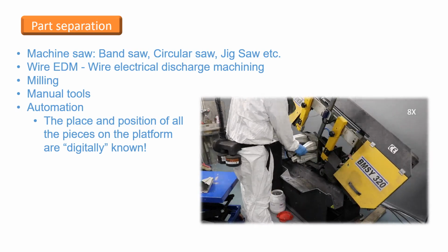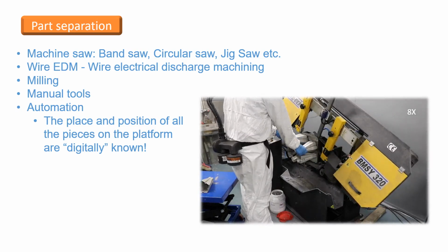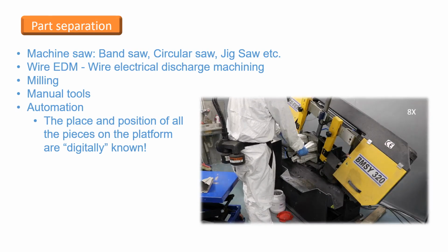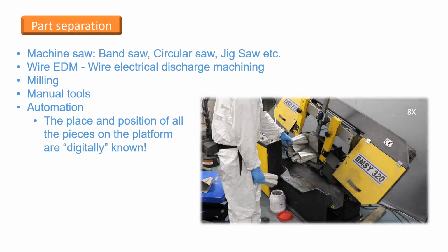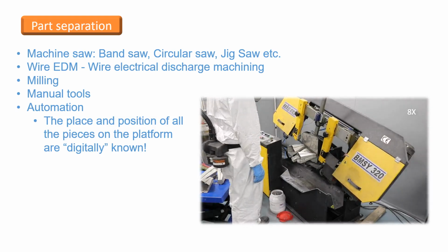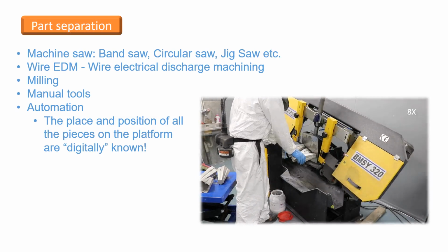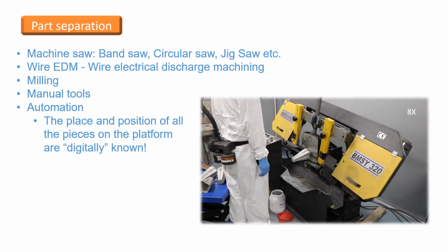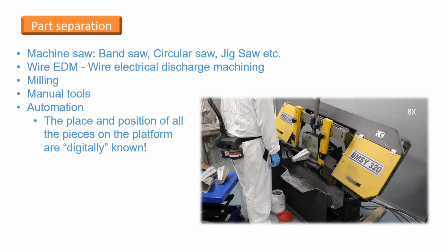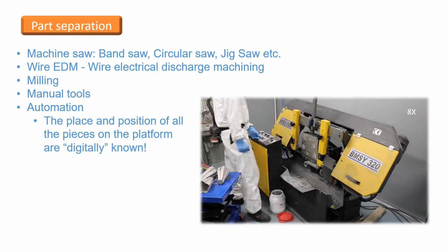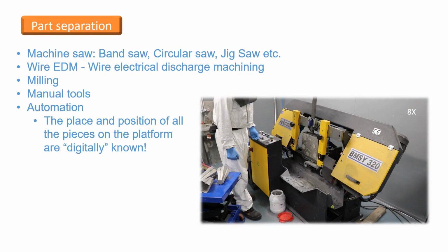It is typically about 3 mm for a bandsaw, depending of course on the saw used. When using wire EDM, the working margin is about 0.3 mm, depending, of course, on the hardware used and the thickness of the wire. The advantage of the wire EDM method is a good surface quality. The sawing surface is often good as it is. The method can also be used to saw the shape. In some cases the parts no longer need any other finishing. The downside of the wire EDM is its slowness.